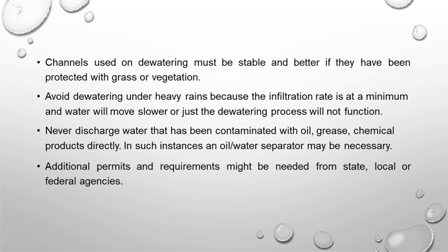Okay, so first, during the outward stroke, atmospheric pressure is acting on the surface of the water, which helps push the water into the cylinder. During the inward stroke, the suction valve closes and the water is forced up into the delivery pipe. As we can see, the construction of a single acting reciprocating pump consists of a piston, cylinder, suction valve and delivery valve. The working of the reciprocating pump can be easily understood.